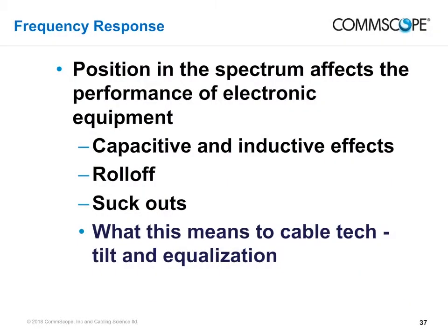Most of the electronic circuitry and physical plant that we use in cable has properties that vary with frequency. Collectively, these effects are known as frequency response. Most of frequency response is due to circuit properties called inductance and capacitance. A more detailed discussion of these topics is included in the Power Theory Primer, but for your understanding of spectrum, it is sufficient to know that capacitance and inductance are common causes of variations in power loss, current flow, and voltage levels that depend on signal frequency.